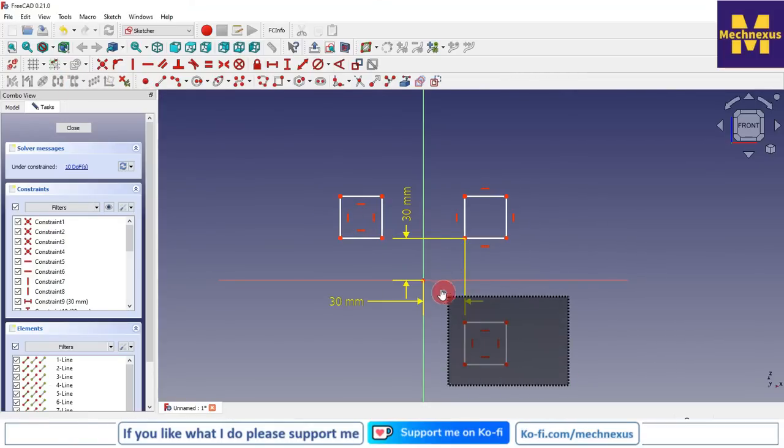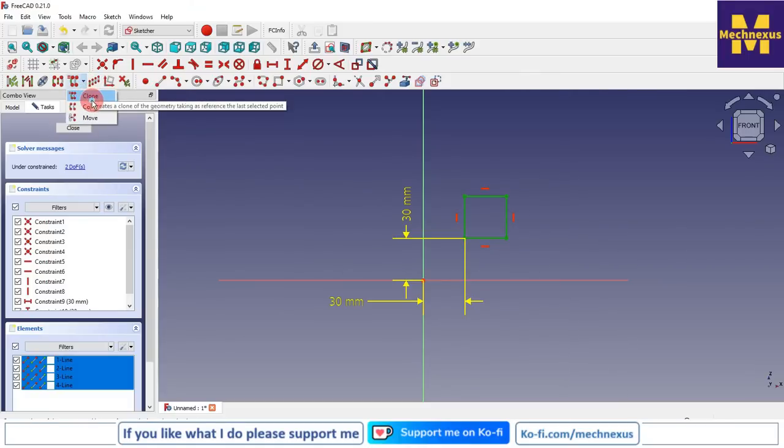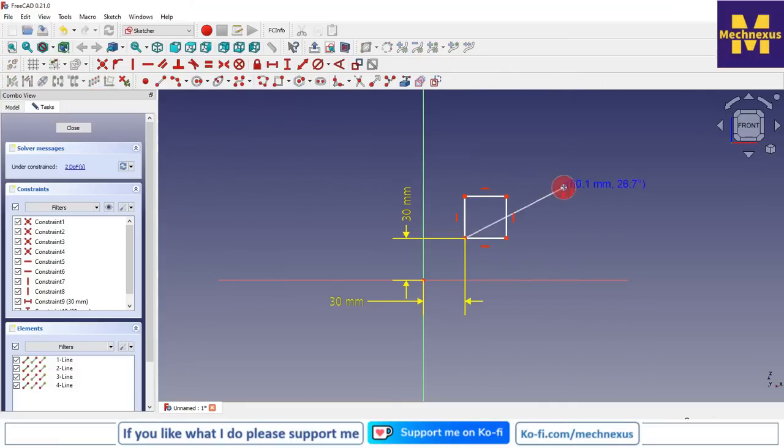Now I show you the next tool in Sketcher, which is clone or copy. So here is a clone, copy and move options. So first we will select all the sketch entities. So here I have selected my square and I will click on the clone. So you can see that I am seeing a line which is the placement line, and if I click on it, so you can see that it got cloned